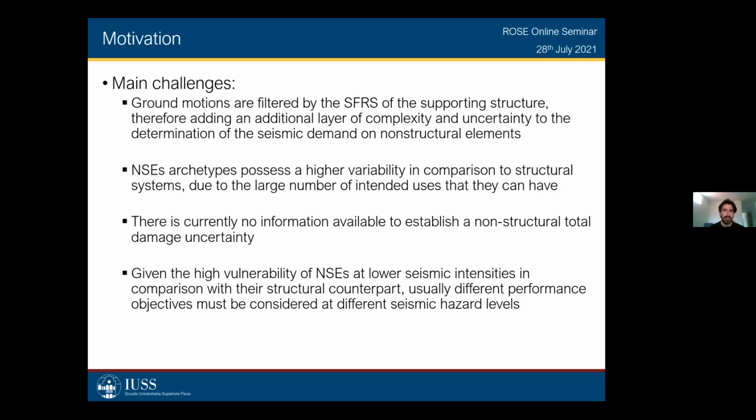With non-structural elements, we don't have this. It's much more complicated because, for example, you can have pipe rings for a piping system in a ceiling, and then you can have partition walls, and these two have completely different layouts, completely different geometric characteristics, stiffness characteristics, and this complicates things a lot as well, because it increases the variability of the geometry of the systems, and this is not an easy issue to deal with.